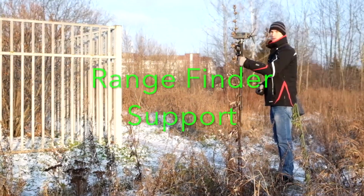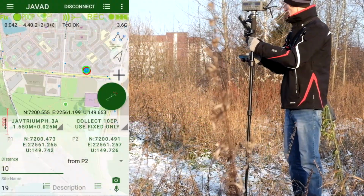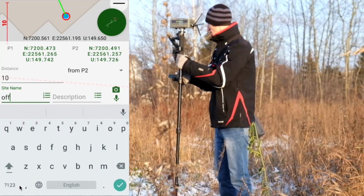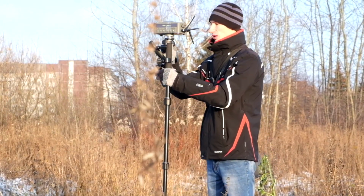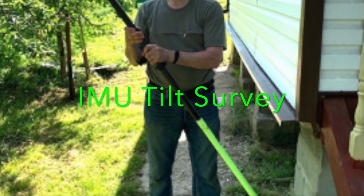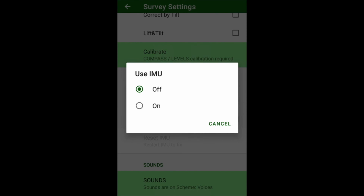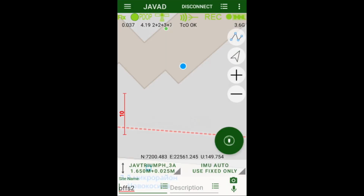And of course laser rangefinders with Bluetooth can be used for such a mode. Bosch and Leica laser rangefinders with Bluetooth are supported. The rangefinders can also be used in COGO tasks the same way. Another option for such points is to just lean the tip of the pole with the receiver and tilt it. The Triumph 3 receiver has an IMU that solves the task and computes the coordinates of the tip.